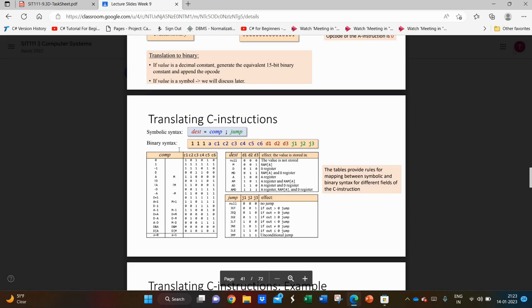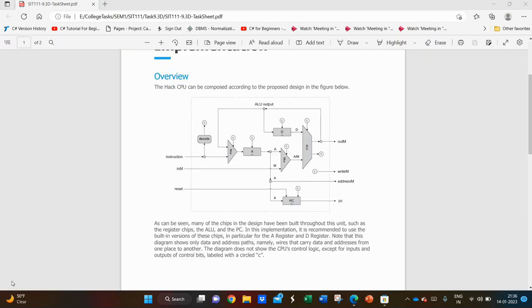Coming back to the inputs again. Input inM is the value of the currently selected data memory register and is the value that the CPU needs to perform various operations. The CPU is connected to the instruction and data memory respectively. The CPU takes its instruction input from the instruction memory and also takes the selected data memory register as one of its inputs. The reset input is a value that tells whether we bring the CPU back into its initial or starting state.